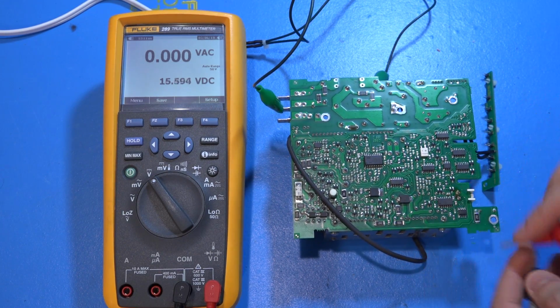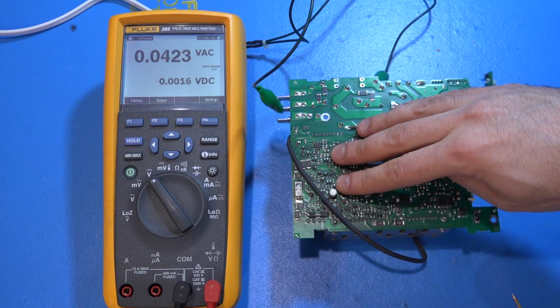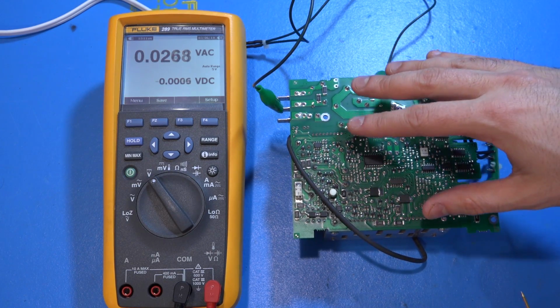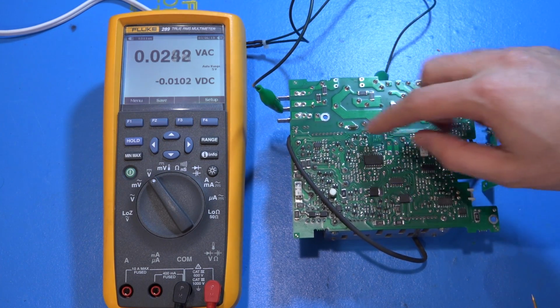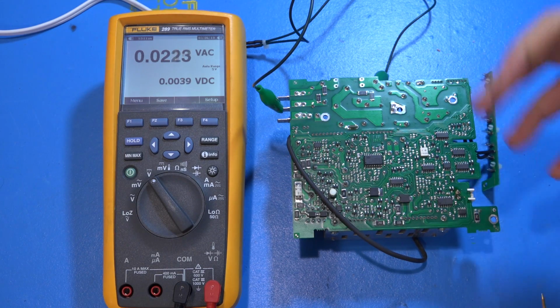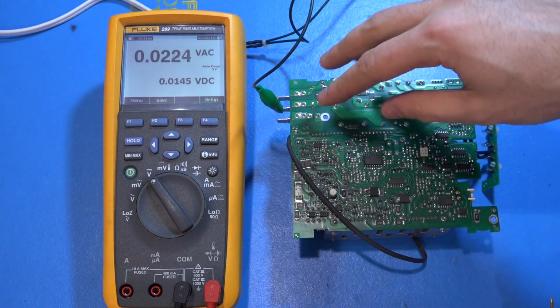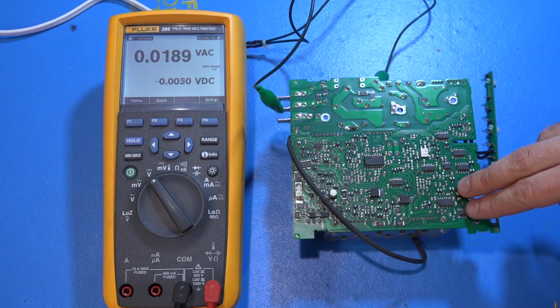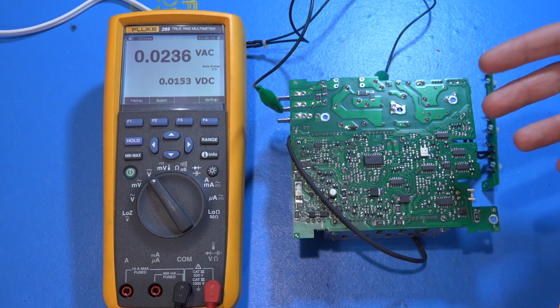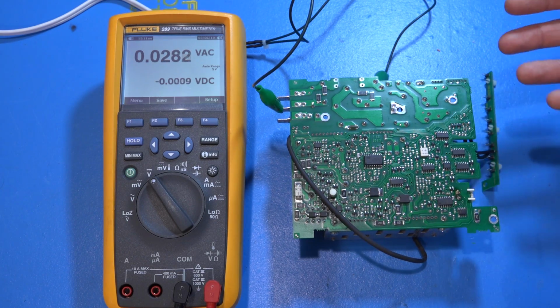It means that there is potentially a short between the capacitors and the transformer, meaning that it is possible for one of the switching transistors to have been completely shorted and therefore creating a DC path. And a DC path from the capacitors to the transformer would appear as a short circuit at DC, and that would instantly blow the fuse.